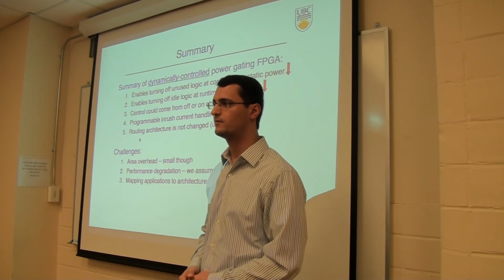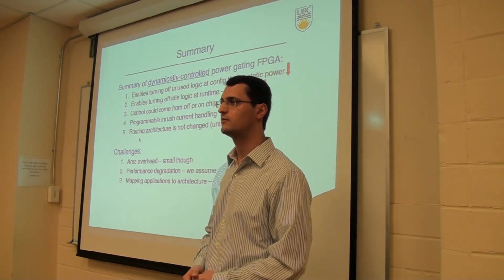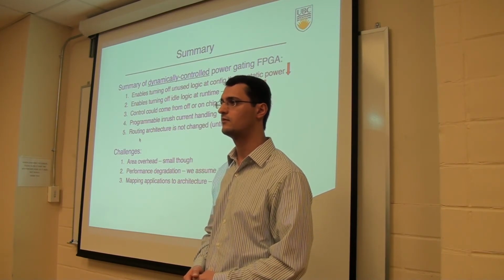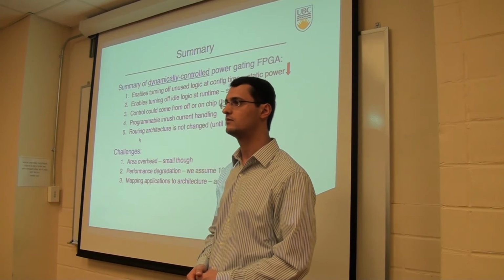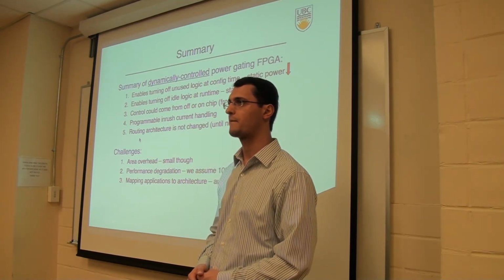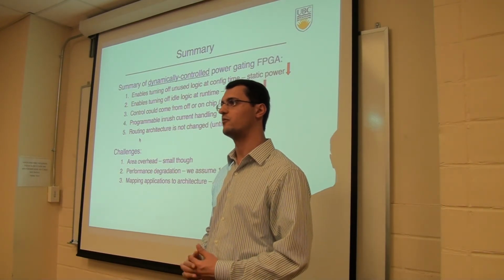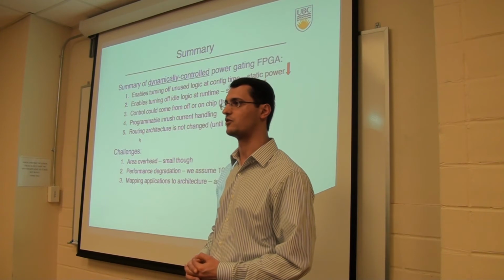From what I understand, you said that dynamic gating and static gating were very similar. But for static gating, you're turning off sections of the FPGA you're not using, so you can gate out the SRAM bits and storage elements as well, right? Shouldn't that decrease static power significantly? Well, that assumes these components have large static power.